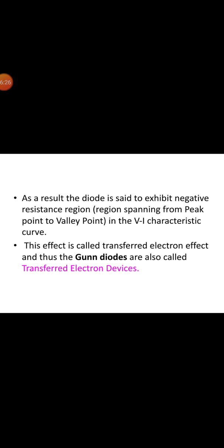In this mode, the Gunn diode is placed in a resonator, which is tuned to an oscillation frequency of F0. In this mode, the device can be biased to several times the threshold voltage. As the input RF voltage increases above the threshold voltage, the device remains in the negative resistance region, and the oscillating frequency is determined by the external components only, but not by the transit carrier time.